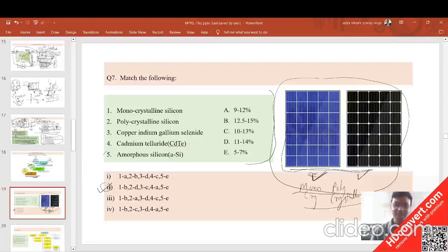That is the good thing. You are not recognized, but there is a trick that you can say that this is polycrystalline or this is monocrystalline. Okay, let's come to the answer side. If you see in the center part, first one is a square kind of thing, and if you see the right side image, it is a kind of diamond shape. So there is a physical difference between the polycrystalline and the monocrystalline. First one is the monocrystalline, and second one is the polycrystalline.